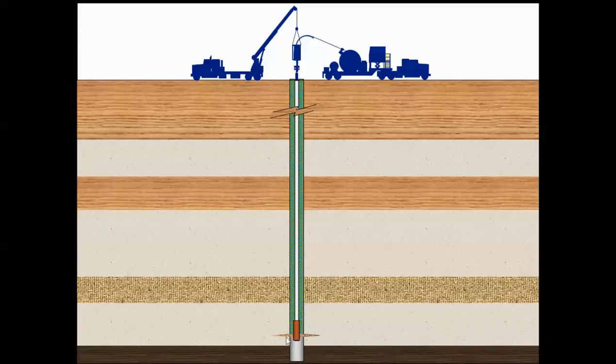So after that, whatever sand slurry you have pumped, you have to clean it out. So you will perform a clean out in a forward circulation. So what is forward circulation? It is when you pump through the coil tubing unit and take the returns through the annulus. Okay, this is called a forward circulation. So you'll clean out everything so that you do not leave any sand in the wellbore.